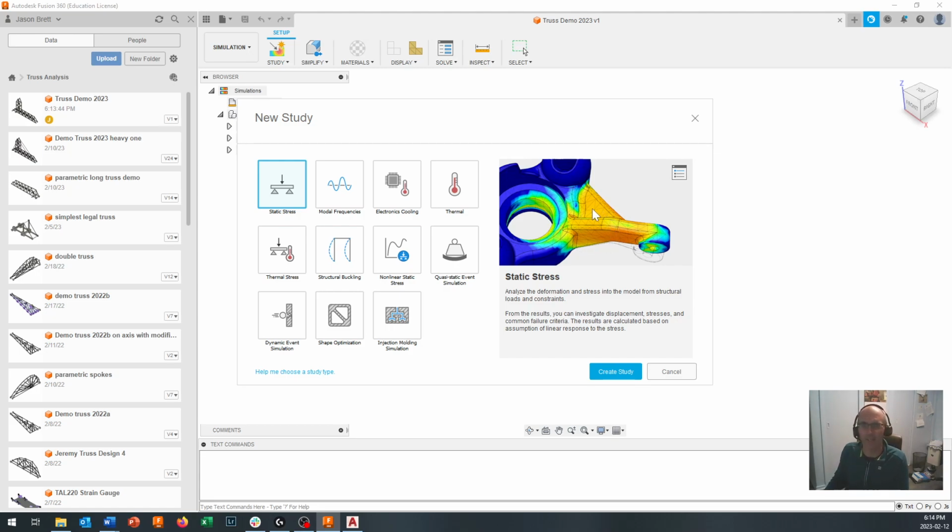And one of the reasons is that because when you do this solving technique, you can see on this image right here that the surface is all broken down into elements. That's what it means by finite element. You break this very complex surface down into a finite, countable, number of elements, little parts. And then you analyze how each little part interacts with each other little part. And through doing that, you're able to predict how the entire structure is going to change under load.